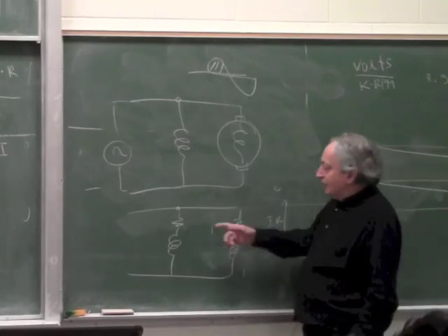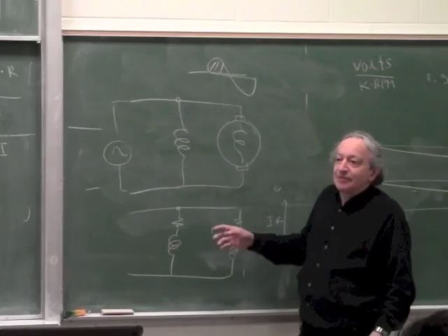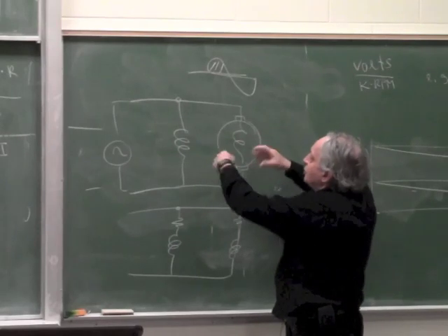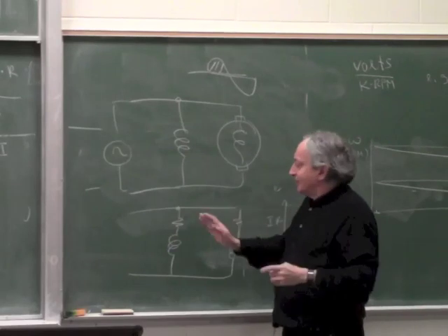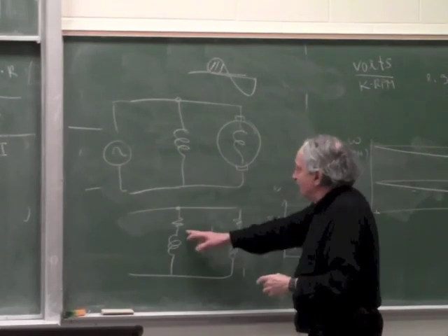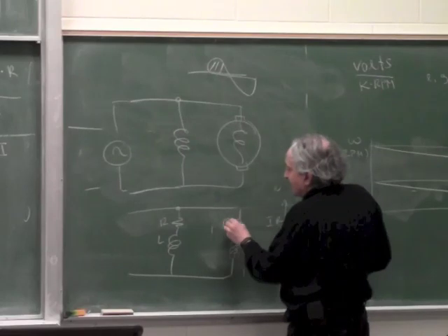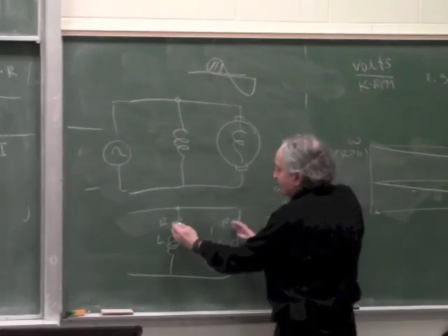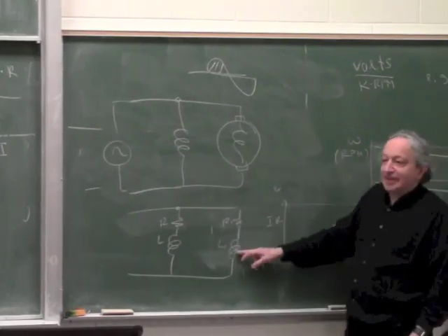Now when you have different ratios of inductance and resistance, you have different phases, so the magnetic poles don't switch together at the same time. There is a small phase shift, because if this is a different L over R than this one, say this is R1, L1, and the vectors are not exactly parallel, because the vector depends on the ratio between R and L, right?